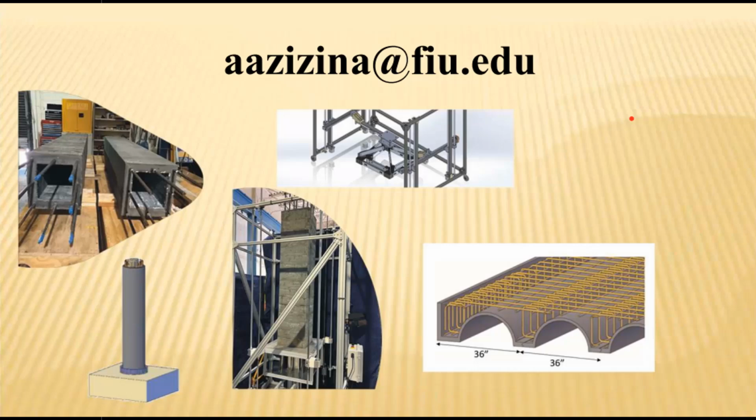Layer by layer. The advantage is that it's fast. The disadvantage is that you cannot put the reinforcement inside. But if you combine it with shotcrete, it basically sews the different layers together. Okay, so we are looking at shotcrete at the nozzle level, not shotcrete after it's hardened.